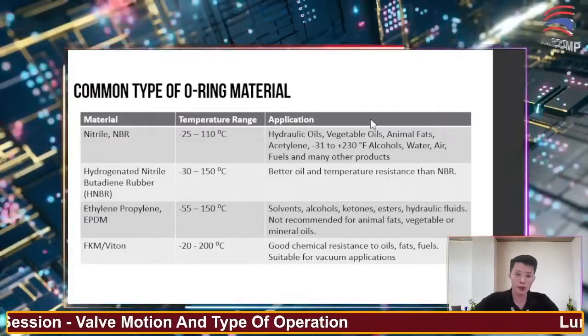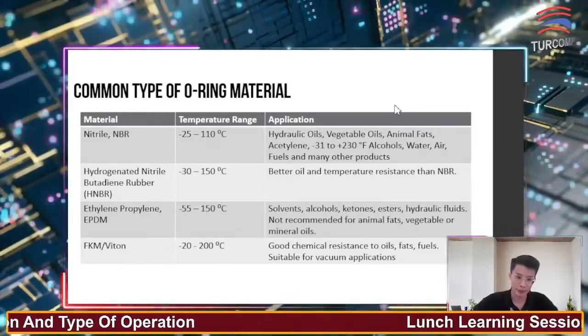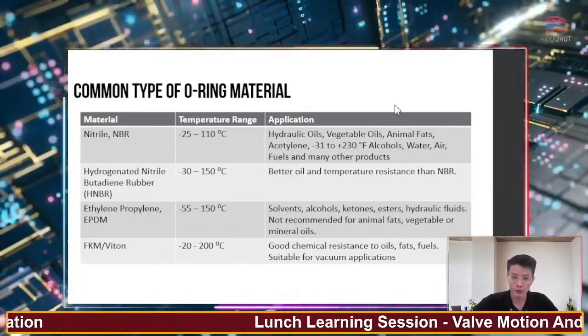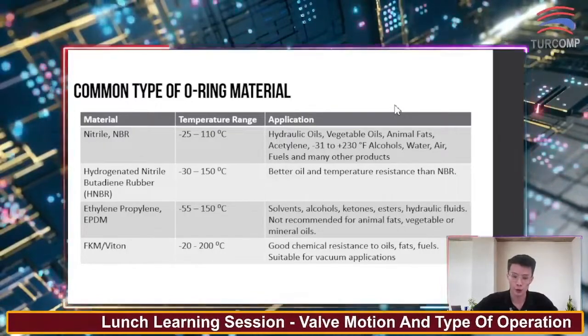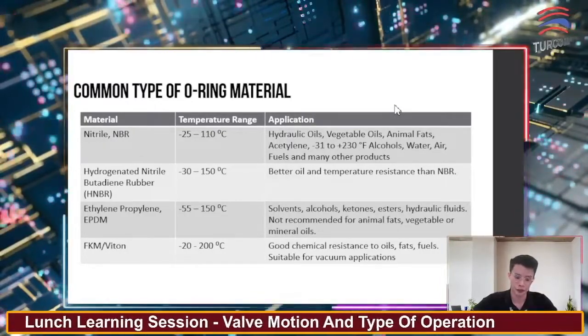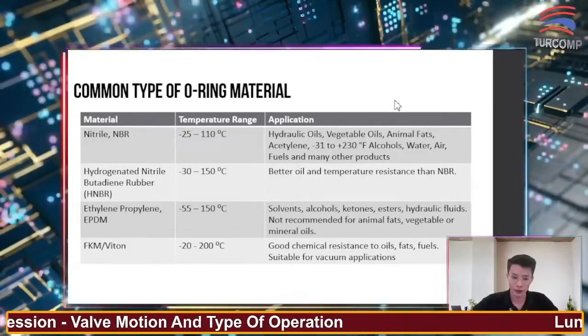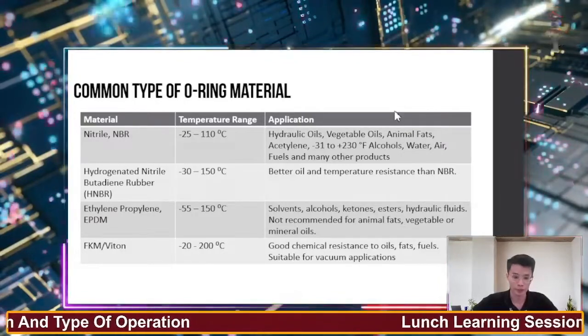And if you want a tight shut off, then you can choose the linear type. It is a good option. And if you want a control type, like if you want to use it as a control valve, then the linear valve will also be more stable because it can achieve a more accurate control. So it depends on your application. Then you can decide whether you want to go for a linear or rotary valve.